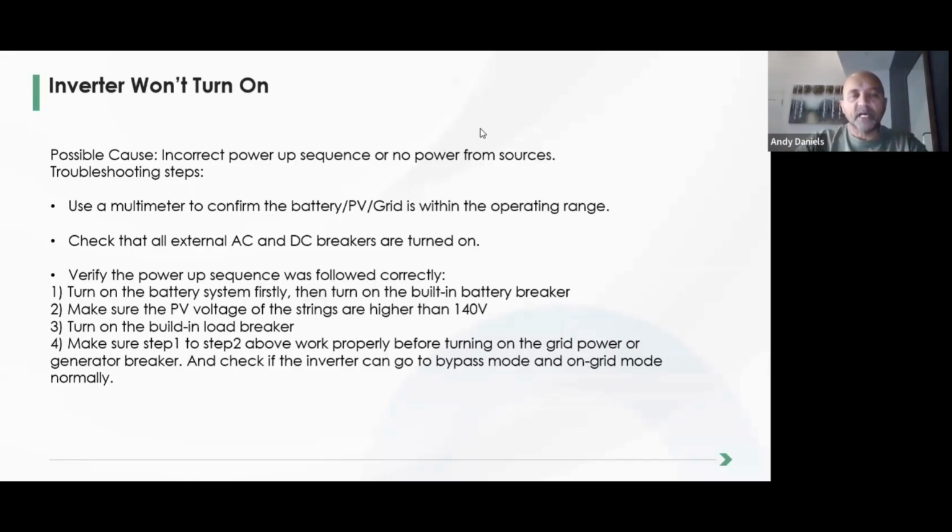I also, in the past, would have liked to encourage installers: you can power the machine on with AC. The reason I like doing that is because when you do that, you're given a chance to set the battery type. Because previously, in our very first iterations of machines, we wanted to prevent an inrush of DC current if you powered the machine on by battery only.